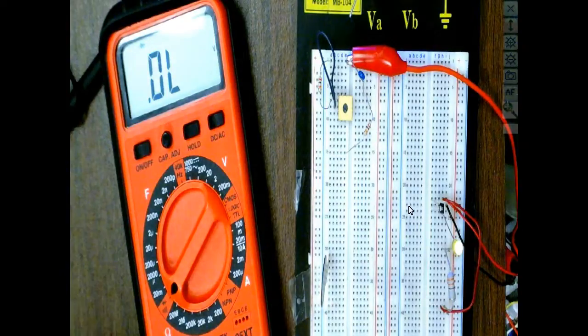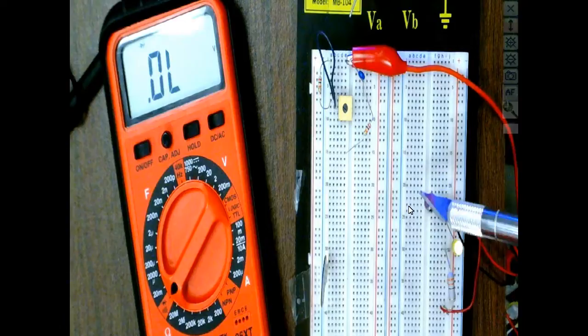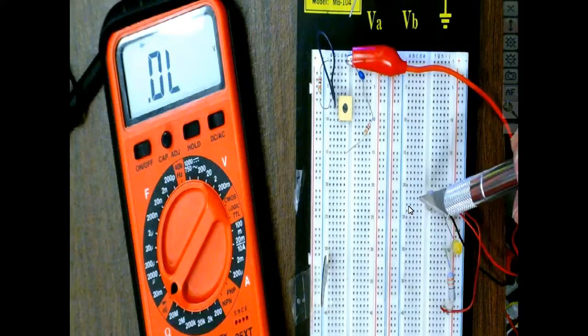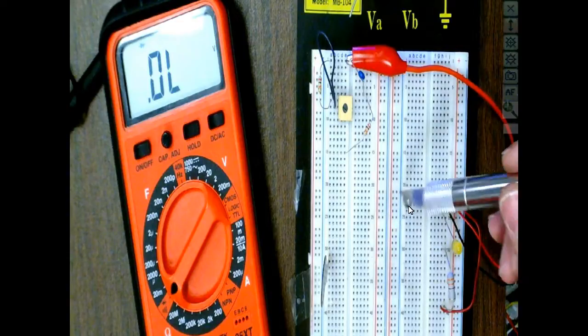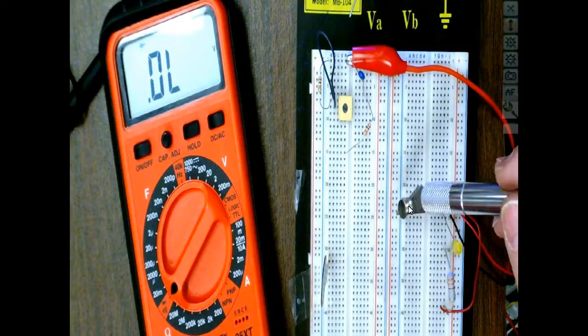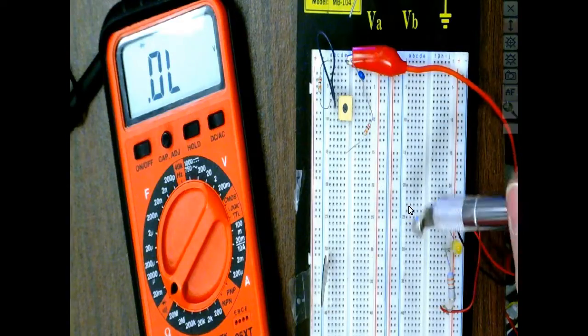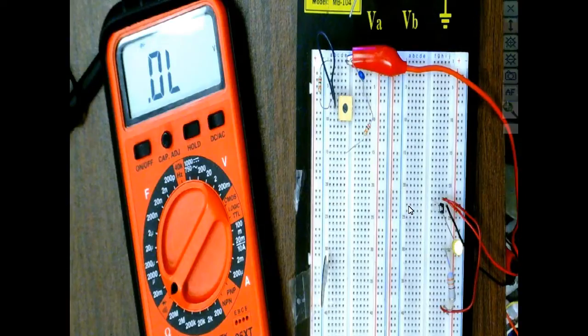Let me put the magnet on my X-Acto knife and see if we can do it this way. Off, on. So here it comes in this direction, turns it off. I'm going to flip my X-Acto knife around. Of course, it's got a magnetic field there, and this turns it on. And we call this a latching Hall effect. So that Hall effect is sensing the magnetic field. It's not sensing the metal, it's sensing the magnetic field.